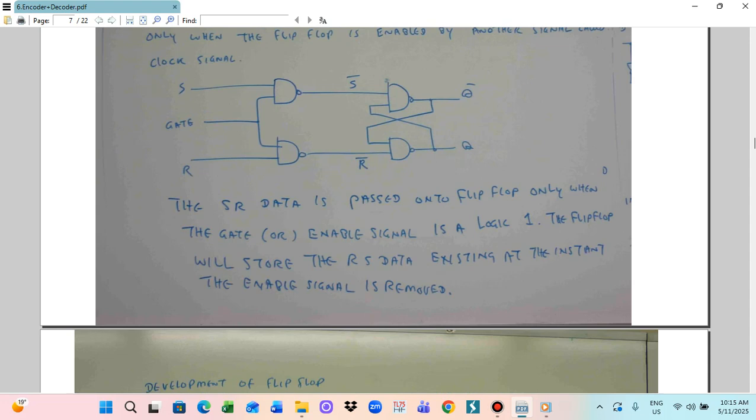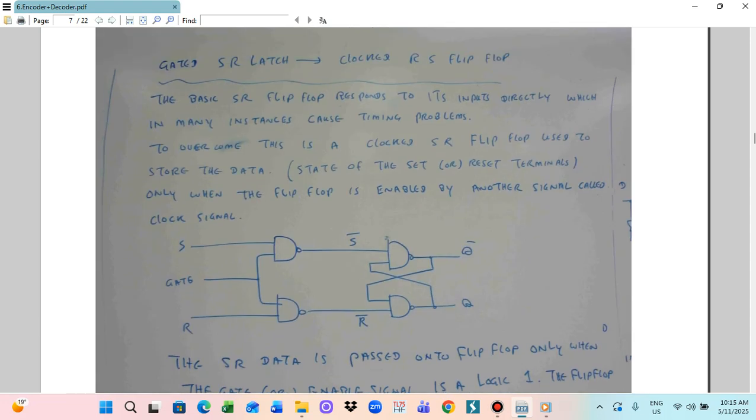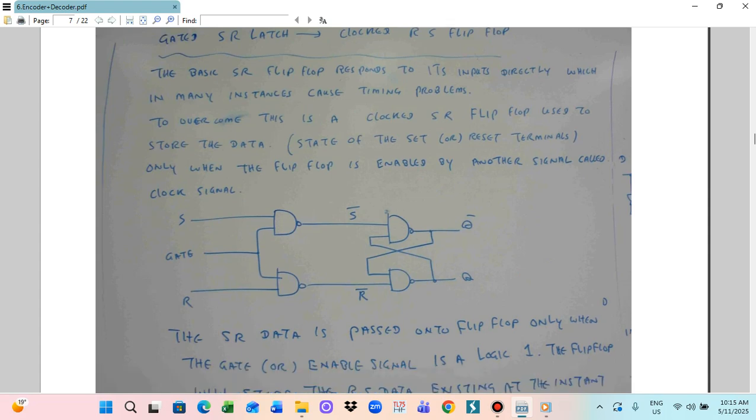So this is the SR flip-flop. The SR flip-flop is just a basic principle. They are not commonly used devices, because some things can be invalid. Some outputs are invalid because when you put S and R both active, the output is invalid. So this is the disadvantage of the SR flip-flop.